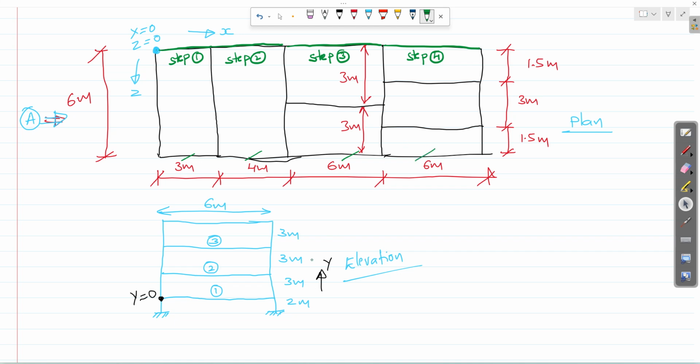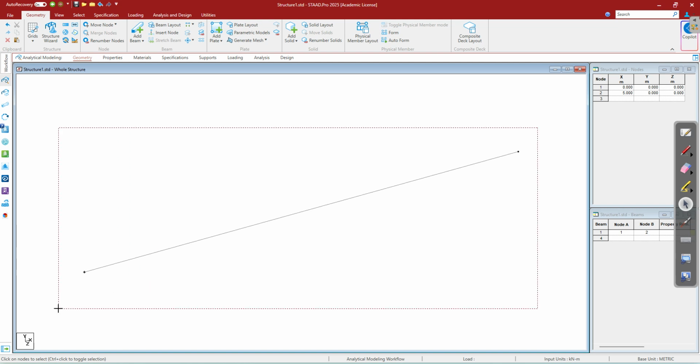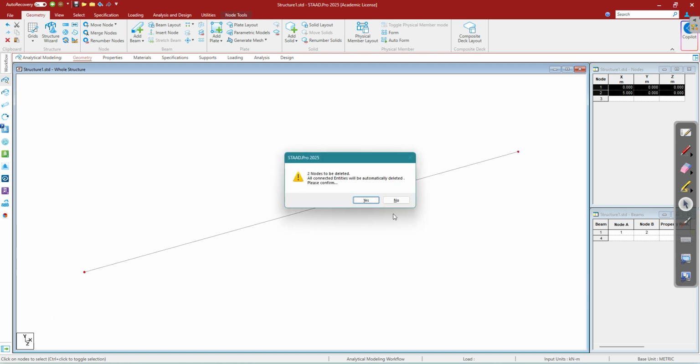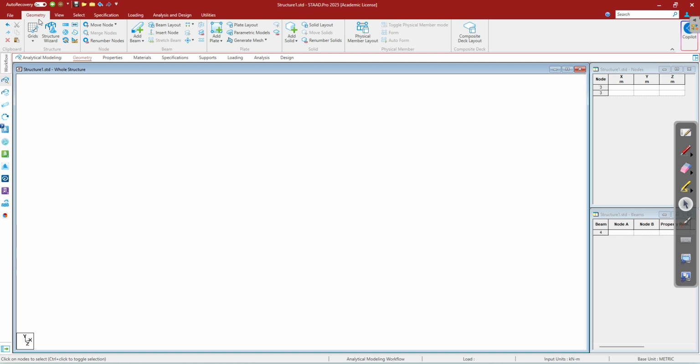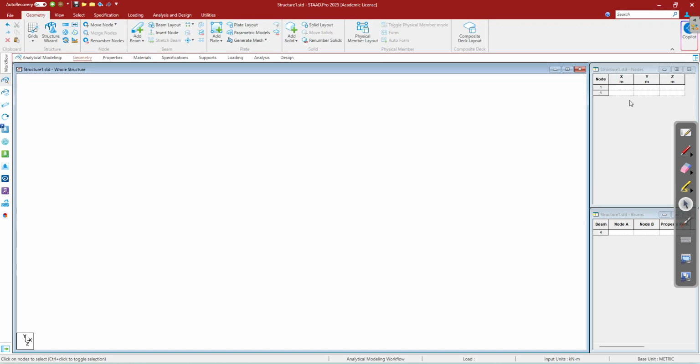Okay, so you go to STAAD, you delete your past model. Okay, first you go to geometry, you create the first node, origin 0, 0, 0. So this is your first node.